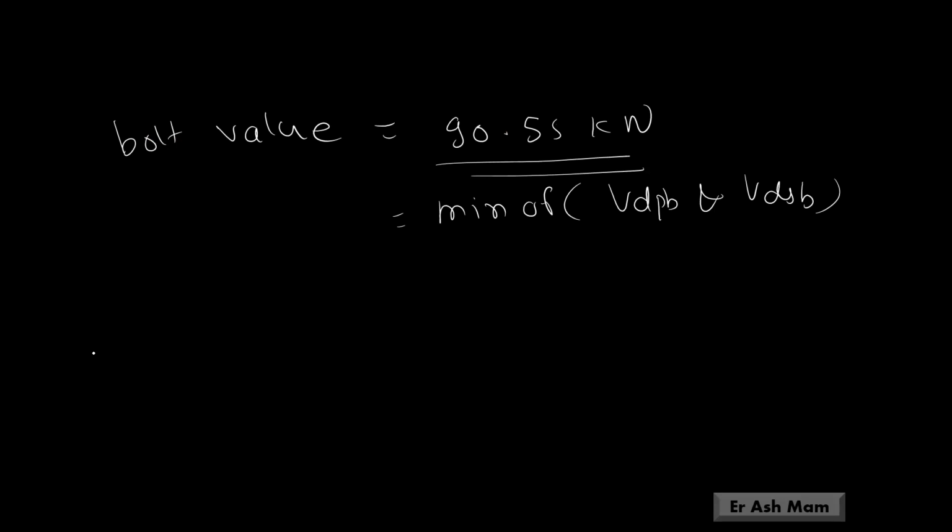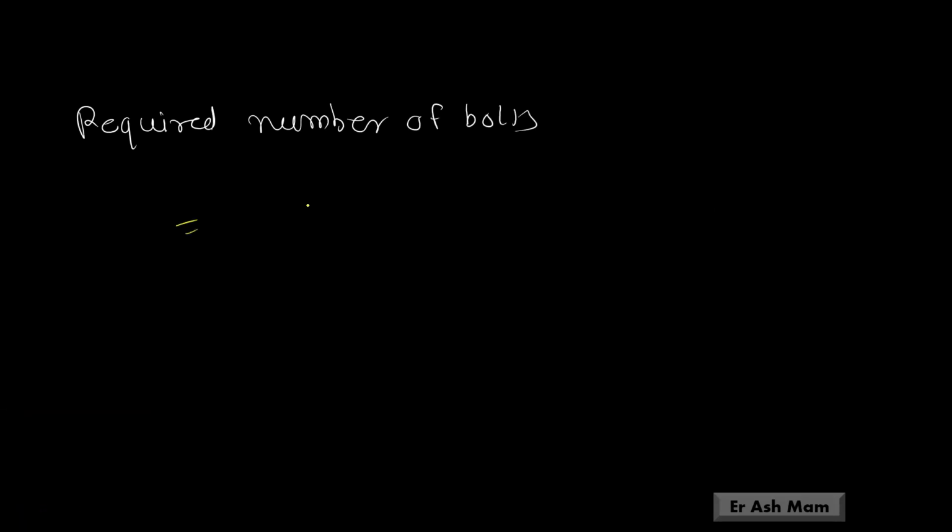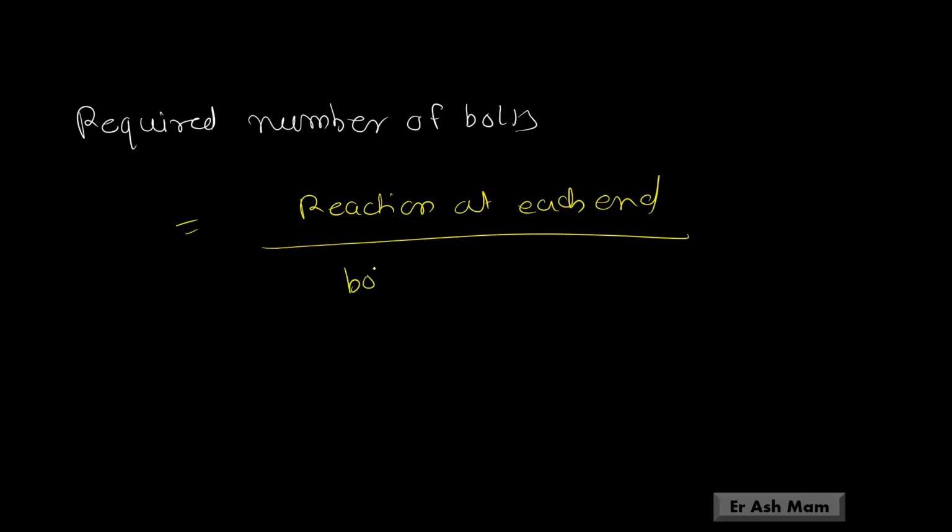The next step is the required number of bolts. Required number of bolts equals reaction at each end upon bolt value.